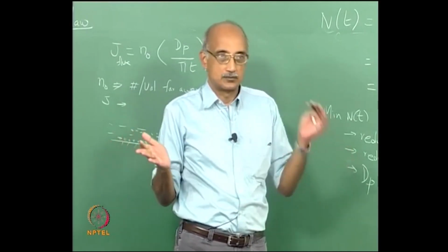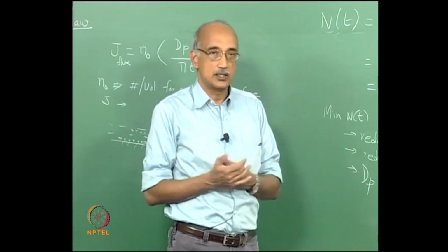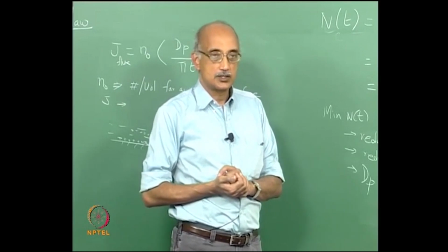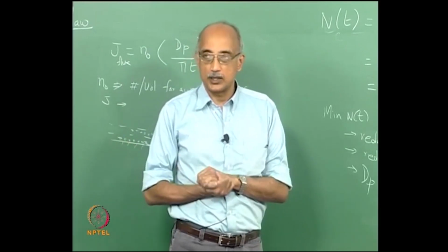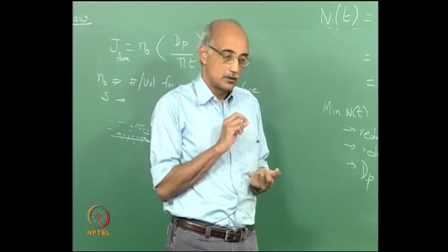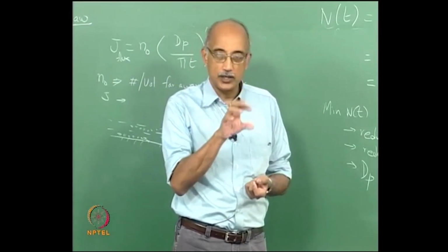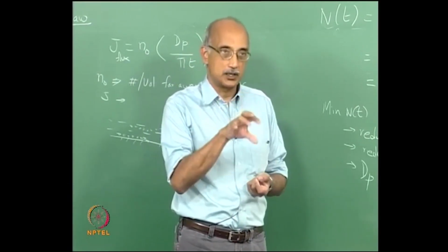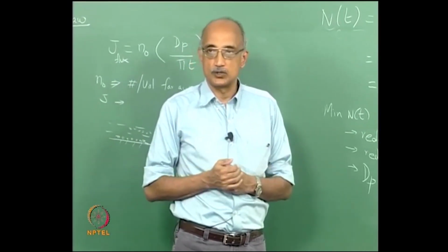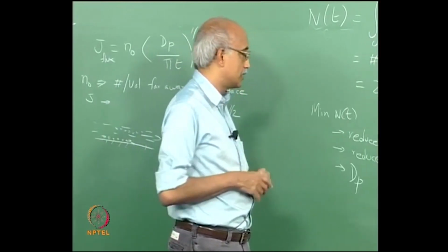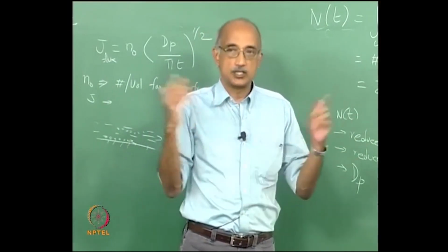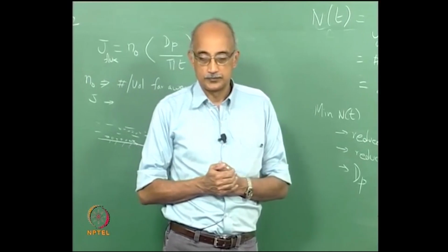You cannot minimize everything. Well, you can, but it's going to cost you so much that your product becomes economically unviable, right? So you have to have a practical strategy. You don't try to get to 0 particles in your product, but you try to have an optimum control strategy where you identify the most sensitive particle sizes and have the maximum containment in those size ranges, and for the less sensitive particle size ranges you don't worry about it so much, okay? So it's a combination of strategies that you need to evolve, keeping in mind a holistic picture of what your product requirements are.